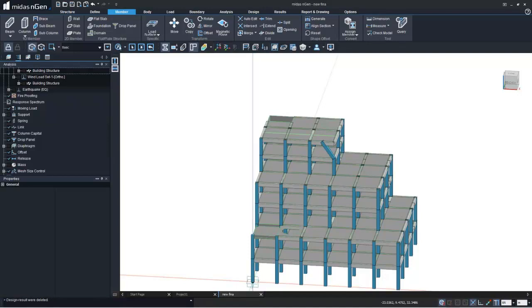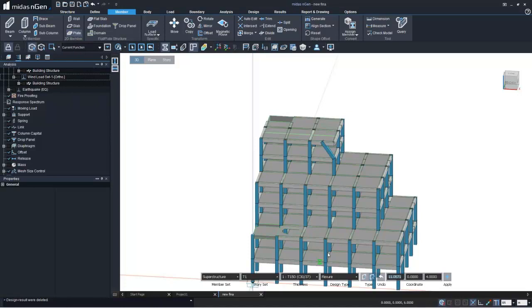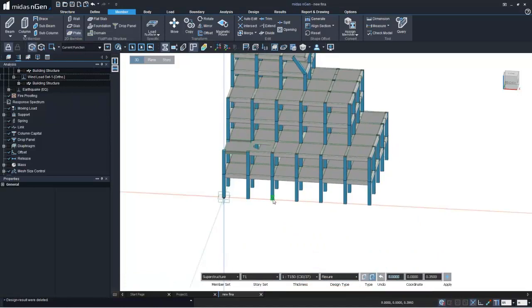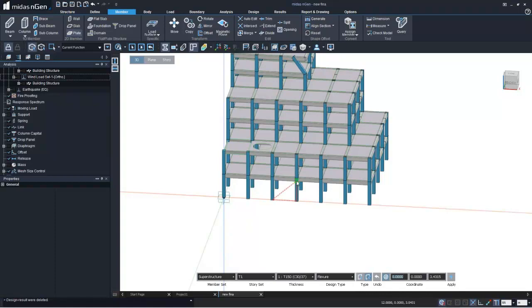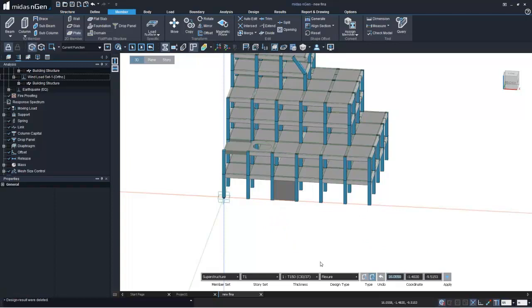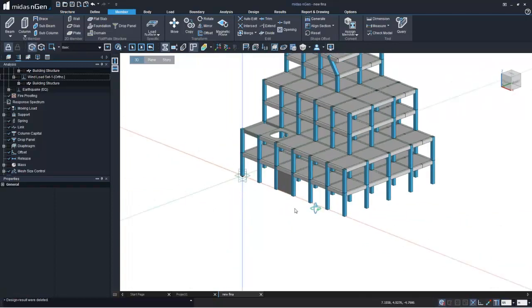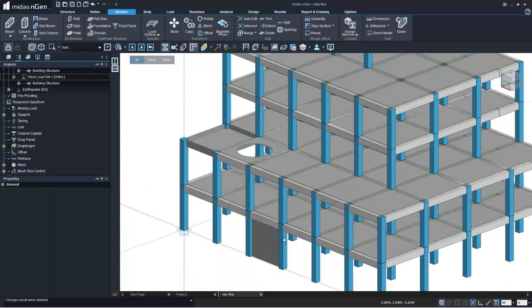Okay, masonry walls, load-bearing masonry walls. Well, yeah, you can include load-bearing masonry walls over here if you want to perform a linear elastic analysis of those masonry walls. So what you can do is you can actually model your plate elements over here, or you can also model the wall as plate elements, but I would recommend the plate elements over here, and just create the walls in this way. Just by 4 points you can create the plate elements. You can create by more points as well, not necessarily 4 points only.